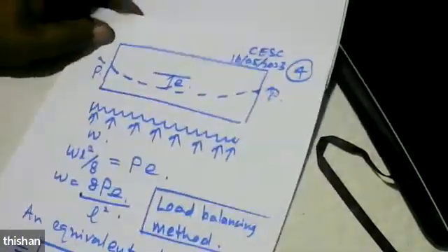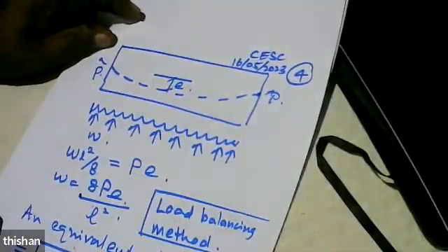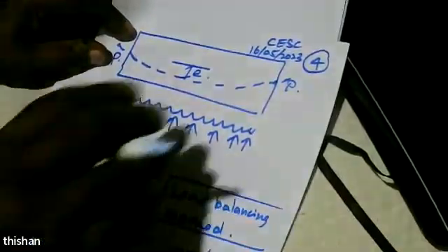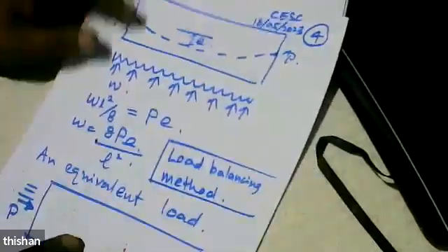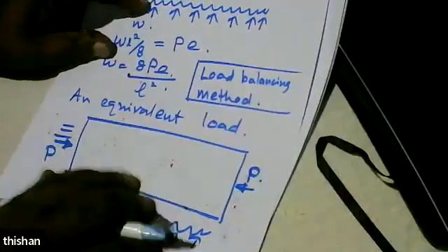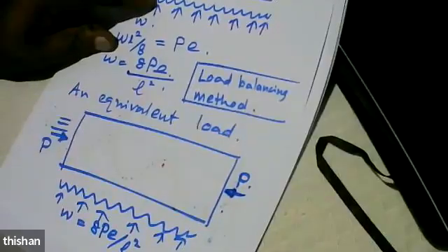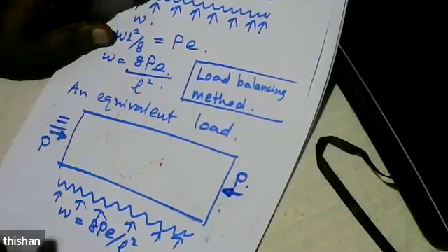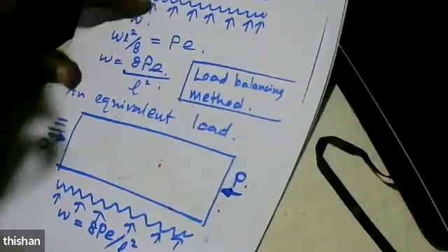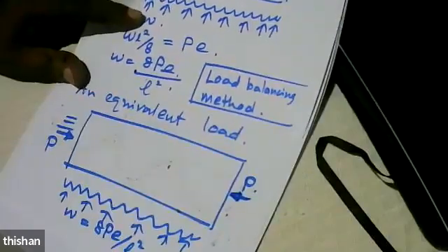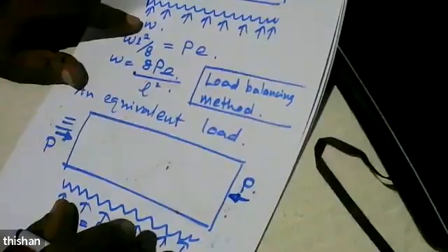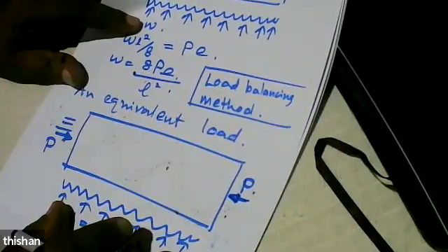So what we are saying is, we have a pre-stress force like this, and it is equivalent to a system like this, where pre-stress becomes axial and the flexural component of pre-stress is represented as an upward load. And this is a very popular method in USA.